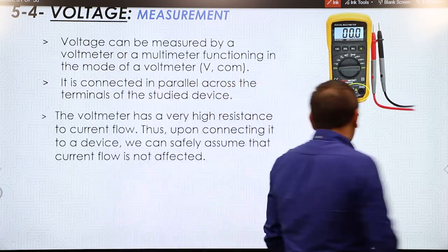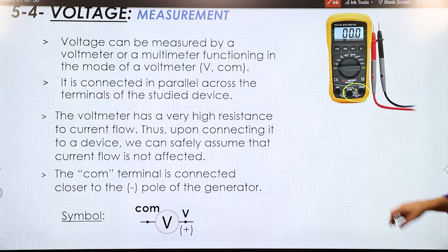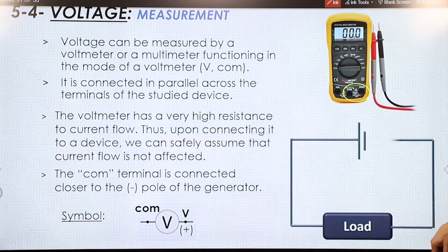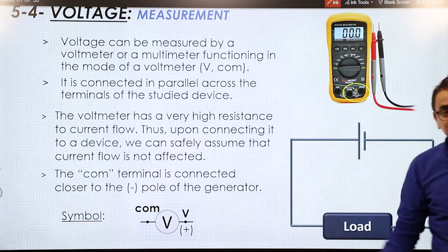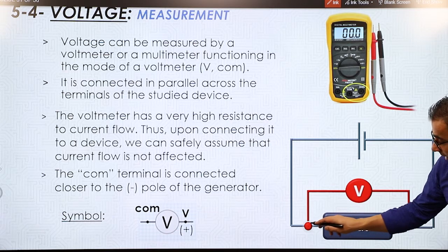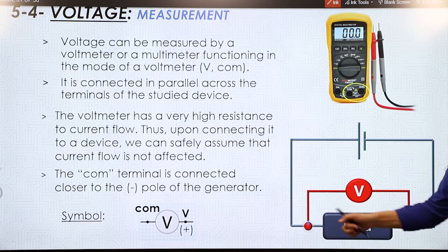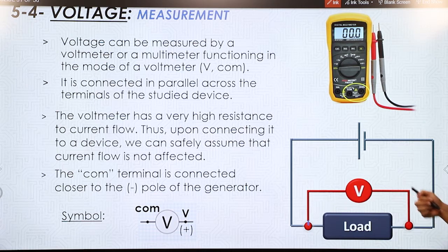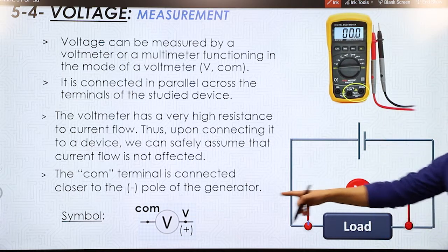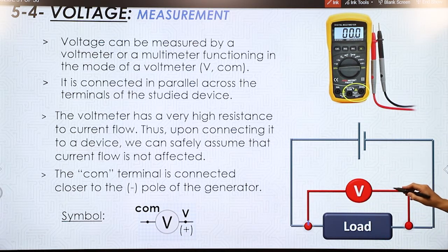Connections in the circuit, okay, let's see them in the circuit, then we read these. Again, the same circuit that we talked about in the previous part. So far this is what we have seen before, right? Now adding the voltmeter, notice the voltmeter I can add here like a connection wire. The voltmeter is connected across the load. And again, the voltmeter has a COM, so I'll choose a convenient color. The COM is always adjusted and placed closer to the negative side.